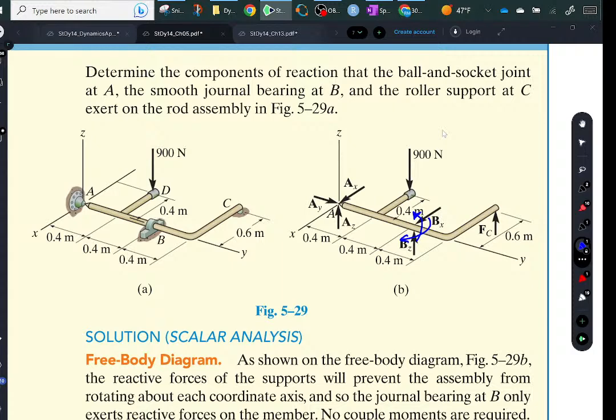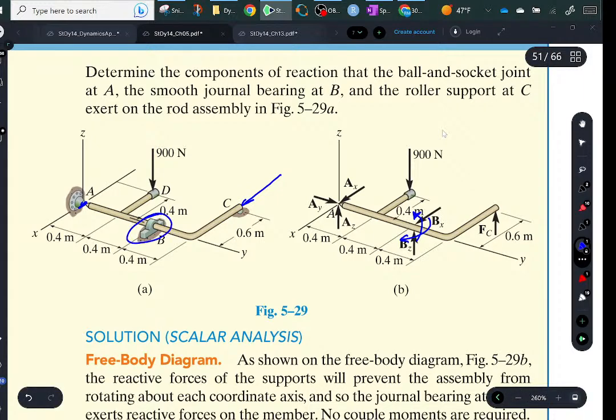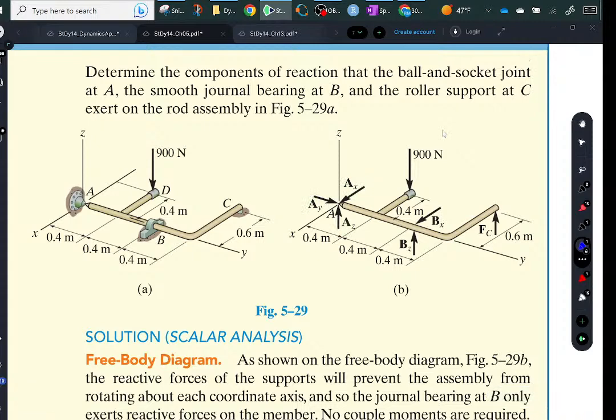In other words, if I went in here and pushed on this, and this was not connected, is this going to take a resistant moment? Yeah, it is. So technically, why is he doing that? Well, because he says 1, 2, 3, 4, 5, and a 6. But if I put the 2 moments in there, I get 7 and 8, meaning it's not determinable. So this one is a mere approximation, and it needs information from mechanics of materials.